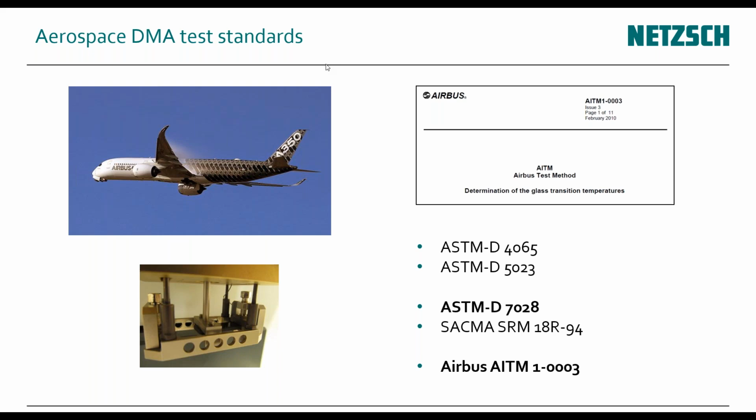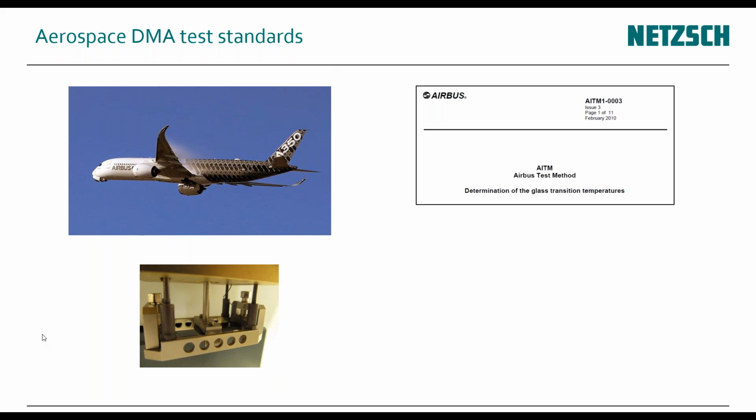Next question: the determination of TG of a composite is more accurate with DMA than with DSC. As he says, because in my old university, we used only DSC for measurement of TG. Let's say DSC has its place. DSC is a very, very straightforward method. You just place a little bit of your sample in your crucible and heat up. You have sample and reference side, and you see the heat flux between sample and reference side, and you can also detect post-process quality control. Why are we using DMA here? Because DMA is just so much more significant, so much more sensitive.